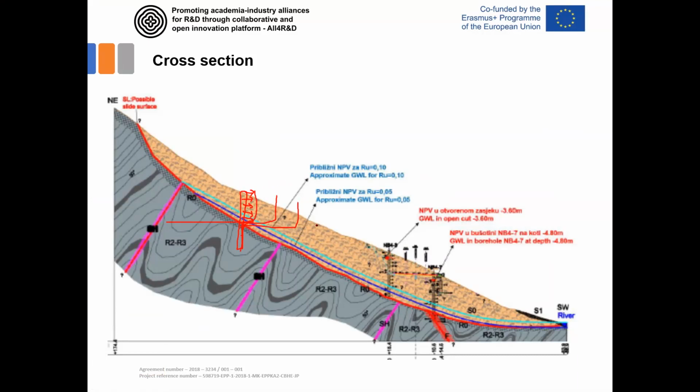If you install the extensometer, for example here, not vertically but in some sub-horizontal position, you have rings all around this extensometer. These rings are grouted and linked to the surrounding soil, but they can slide along this plastic pipe that you saw on the figure.